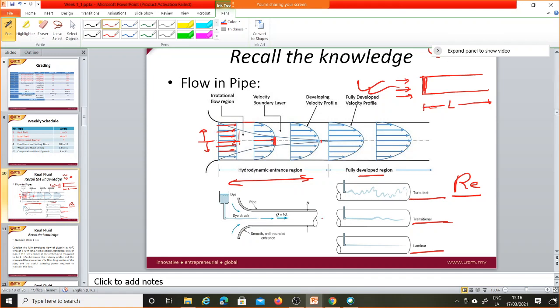Okay, so when the flow inside is very normal, very slow or moderate, we can separate this flow gradually, like a very straight line, it will go like this. So it means that it's separated. We call that one laminar flow. It means the flow is separated. You can visually distinguish the layers or the streamlines of the dye from the flow.